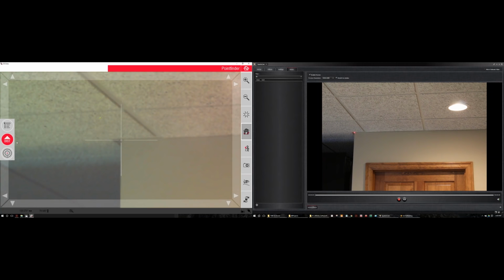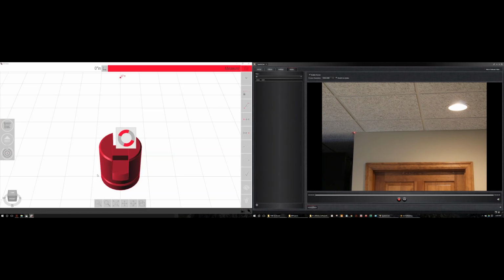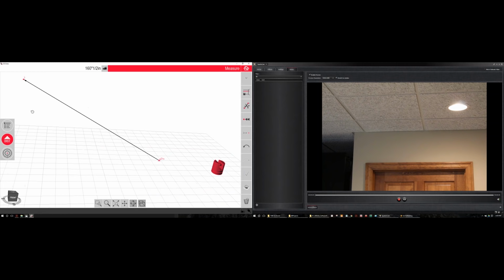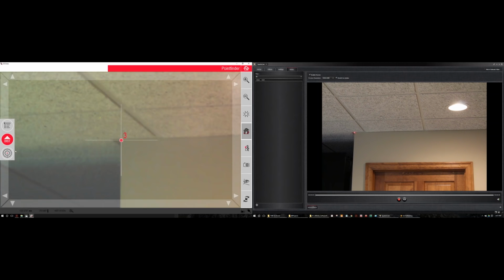So I'm going to take the first measurement, and notice down here there's no icon or anything on it, just a normal thing. When I take the first measurement, we'll jump back to this three-dimensional view of everything, and everything looks great, we can rotate it, life is good. It gets annoying if you want to keep taking measurements. So if you select it once and select it again, it's going to give you a lock here, and then we'll be able to keep taking measurements. So that's what I want to do.